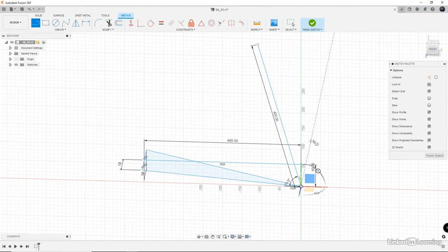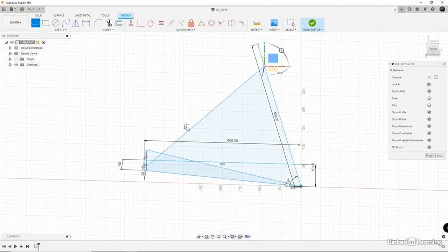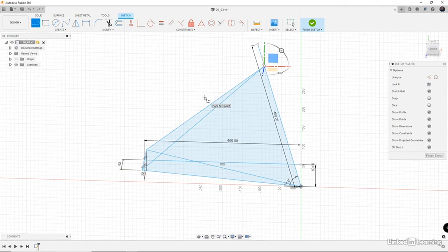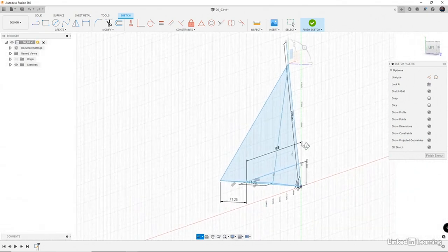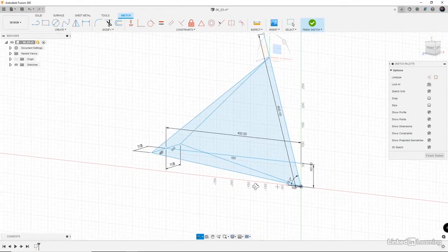Now this is a full 3D sketch, and if I wanted to, I could add more geometry. I could snap this to here, and I could come down on this endpoint, and then I could do the other side here, and then that's an endpoint. So these are all very powerful tools because this is the rear triangle of a bike frame. So if your crank goes right here, all of these angles are adjustable and I can drive this all.